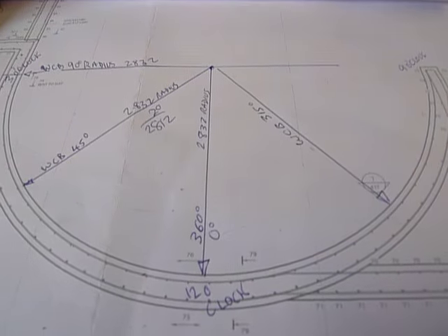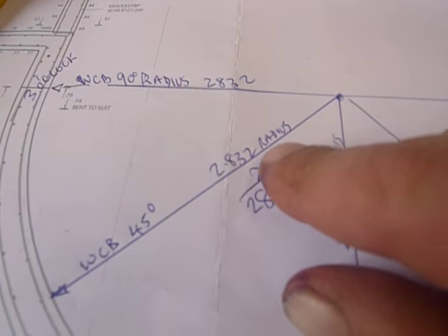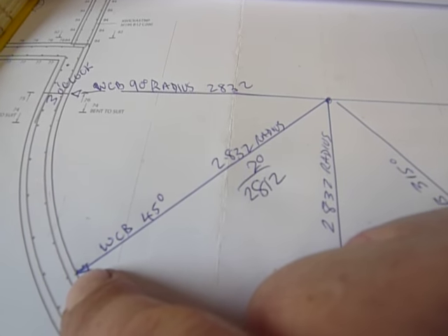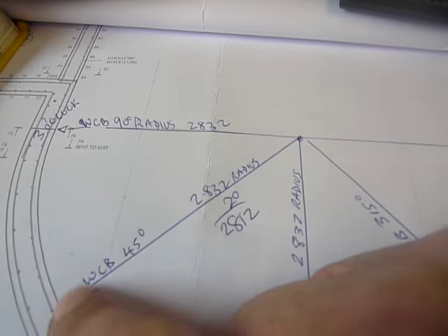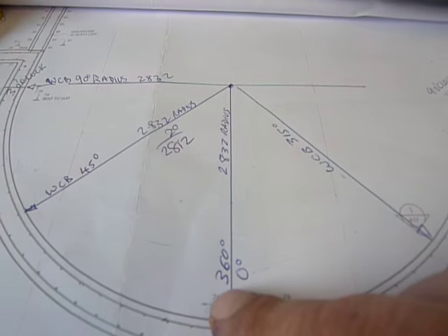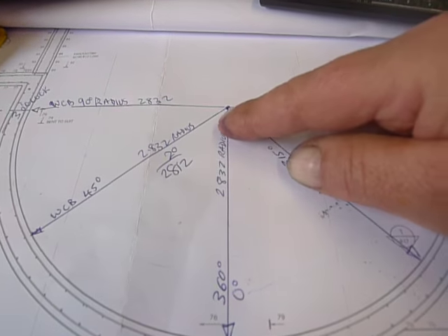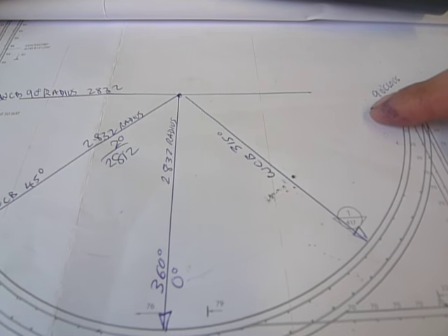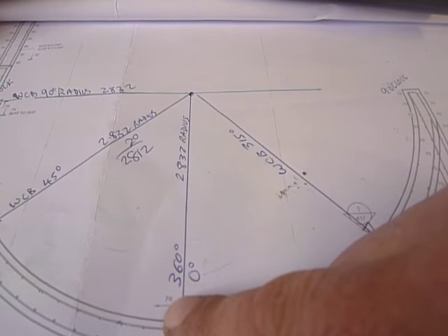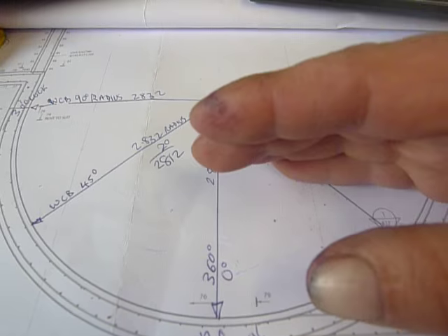The task was that we had a 2 meters 832 radius shutter. That's from the center radius point out to the inside face of the 300 wall, and this is a complete half circle, so it starts at sort of 9 o'clock, goes around to 12 o'clock if we're talking in watch terms, and ends up at 3 o'clock. If we're talking in compass terms, its bearing is 270 degrees in this direction. It goes to 360 degrees there, which is basically 0, and then it goes from 0 to 90. So we're looking at the northern half of a circle.